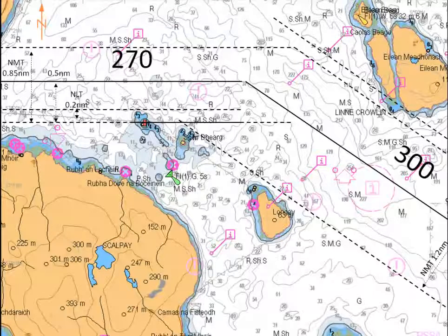PIs can also be used for planned wheelover points in precisely the same way that a wheelover visual bearing is used. In general, it's best to use the point on which you will be running the next leg's PIs as the wheelover mark, as it collapses off-track errors in the same manner as using the wheelover bearing of your next head mark does in visual pilotage.